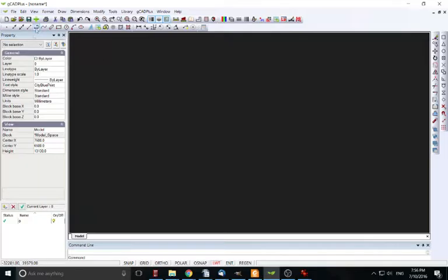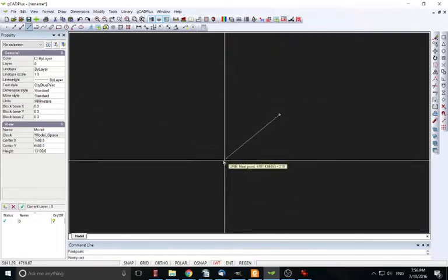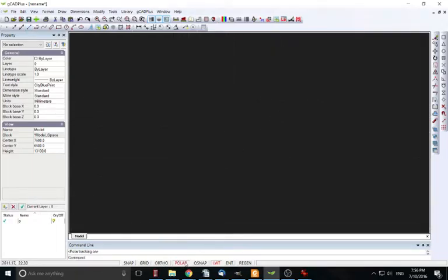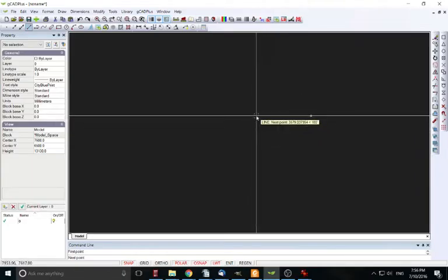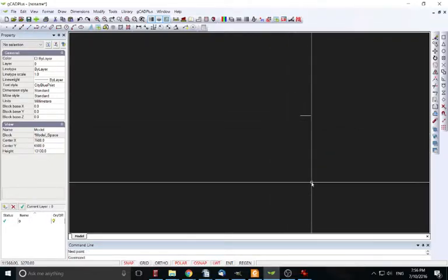So here's our GardenCAD. Again, these videos aren't about how to use GardenCAD per se. It's just about getting things around GardenCAD, like getting a Mudmap onto the page. We've got the poly tracking on, so we can just do that down here. Poly tracking is a very handy tool, like snap and object snap on. It's snapping to 0 or 180 here, and that was at 700. So 700, there's our line there.